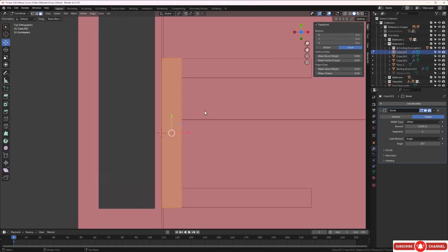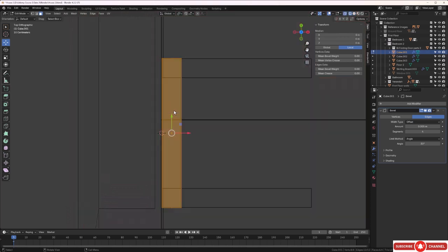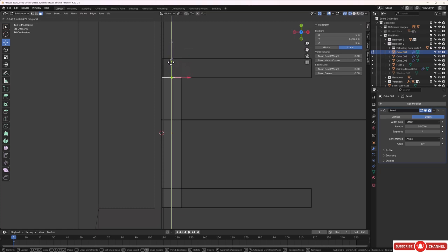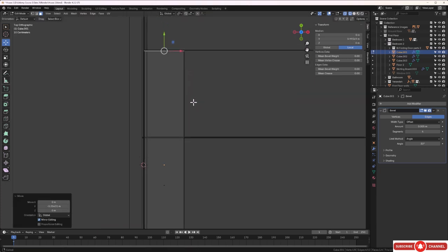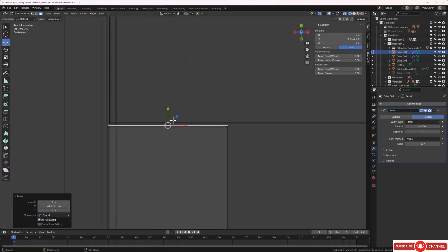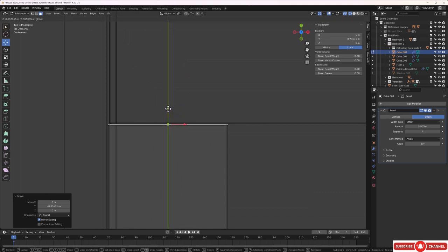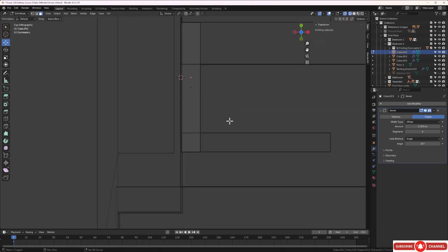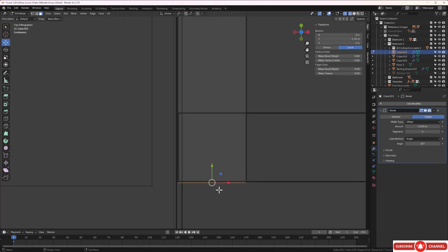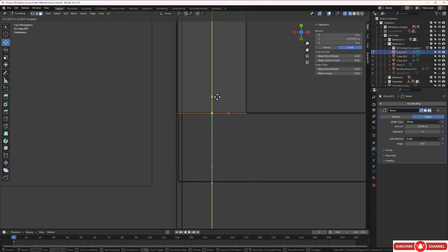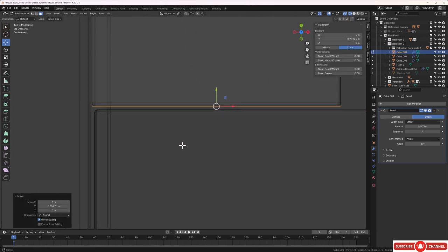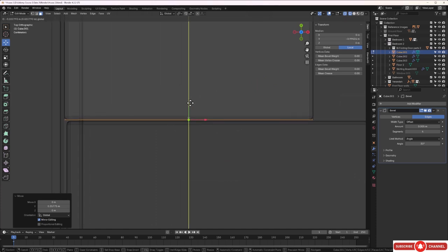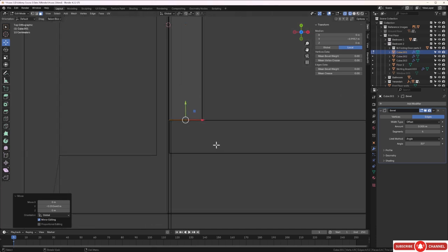Okay. So the next thing to do is grab this block, and I'm going to tap into edit mode with it. And I'll press Z and go into wireframe, and I'll just grab this face here, and I'll just take this back. Zoom in a little bit, and just stop when it's snug up to the other one, like this. There we go, that's cool. I'll do that on the other side as well. And I'll bring this back until it's snug up to the other one. And there we go, that's cool.